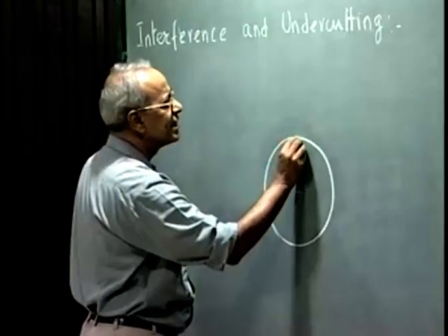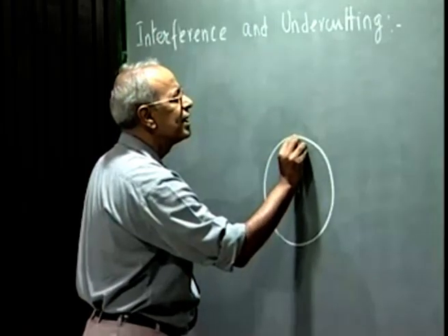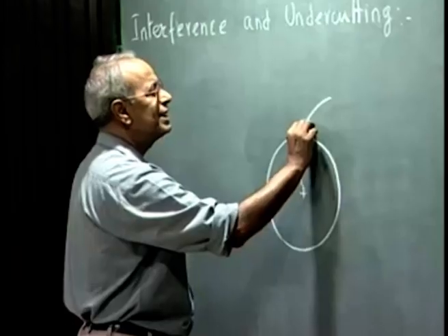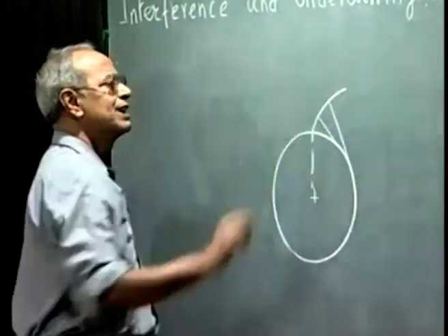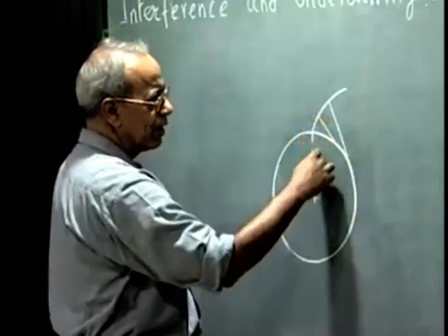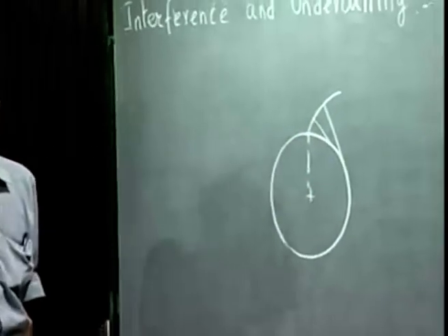Let us say we start from this point A, it starts radially, and as the string unwinds, we generate this involute profile. So, the involute profile exists only outside the base circle, it does not exist inside the base circle.